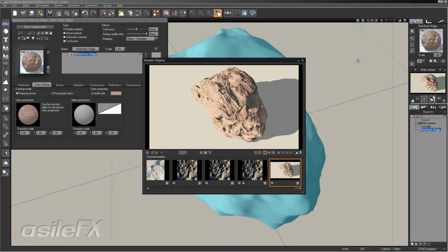And here's a render of that seamless texture map I just made, applied to one of the rocks within Vue. Sometimes it is necessary to invert the Y on the render for it to work on the object correctly because of the different mapping modes and how the texture is being projected onto it. And the easiest way to do that is really to edit the image.